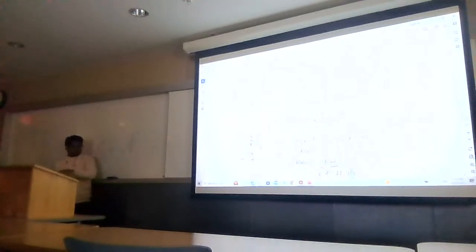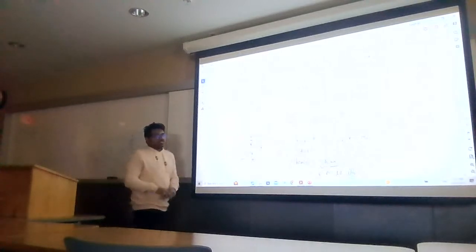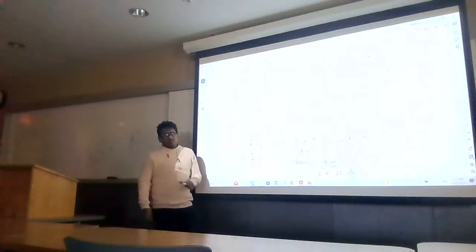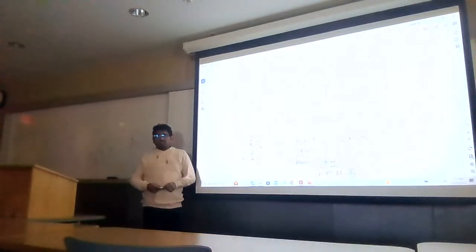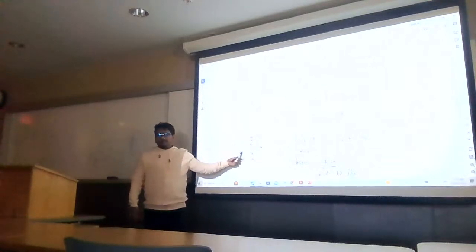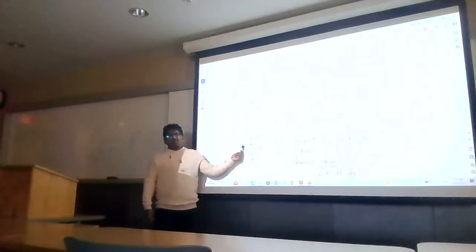We can replace this resistance with a current source. Why do we replace it? Because the output resistance of a current source is ideally infinity, and we will get the maximum gain from this circuit, which has a special name. It is known as the intrinsic gain of a common source amplifier. If someone asks you what the intrinsic gain is, it is the maximum gain which I can find from this circuit. How can we find it? Just by replacing this resistance with the current source.